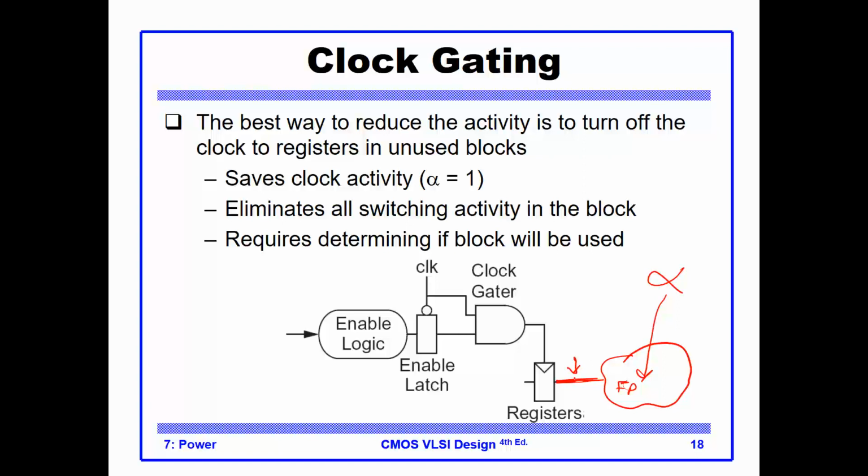How? This is a trick called clock gating, or killing the clock in some terms. Basically, we disable the clock that goes into this register when we don't need the output of this register.